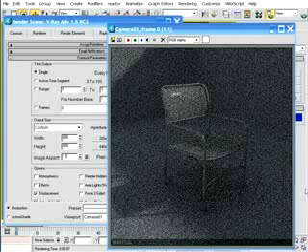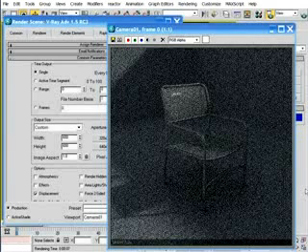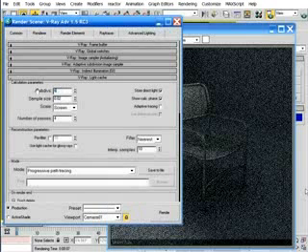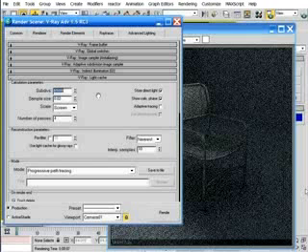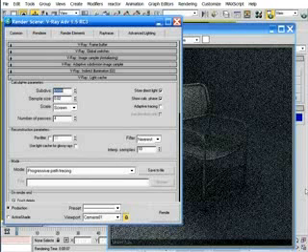So how do you determine the number of rays? You could always just set the subdivision at a really high value, to a maximum value of 65,000, and let the rendering process continue until you get the image quality you need. But just so you aren't blindly using values without knowing what subdivision value will really produce nice, smooth, noiseless images at varying image sizes, you will need at least 1,000 samples for every pixel in your rendered image.